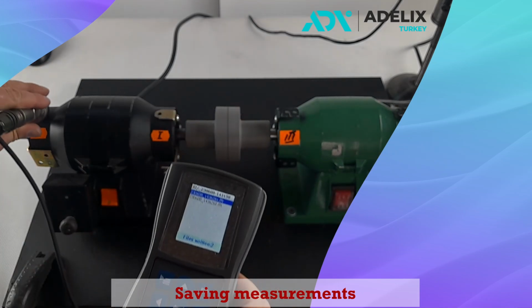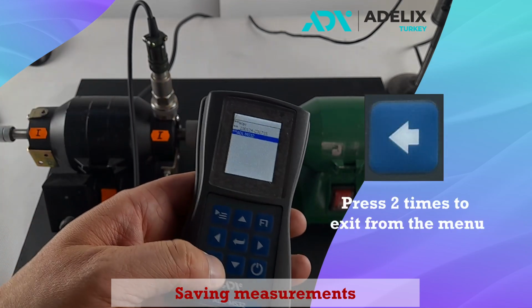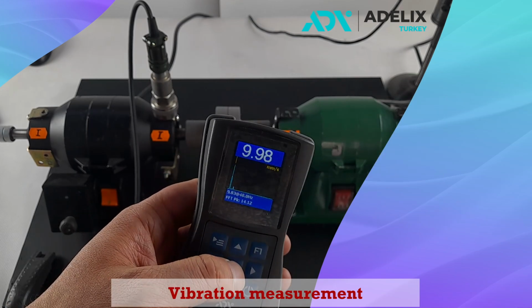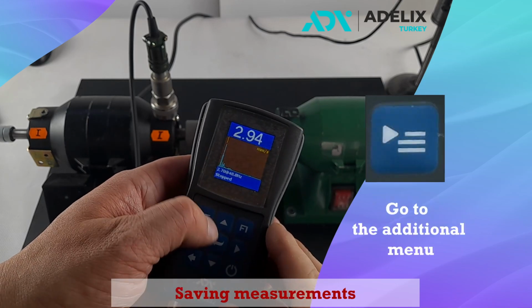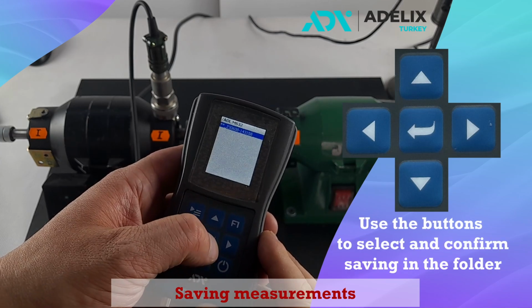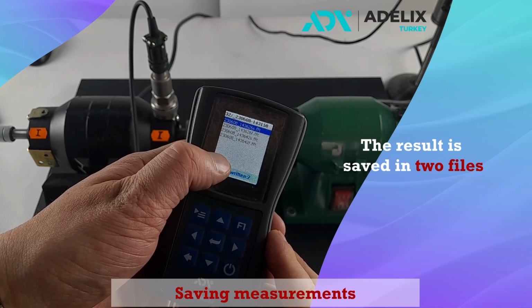Next, we move the sensor to support number 2. We conduct a measurement, and as we can see, the vibration on the second support is lower. We stop measurements and save the result, selecting the appropriate folder. The device saves 2 files.